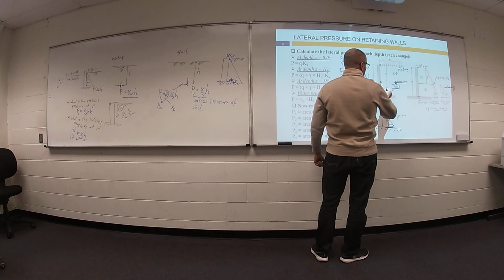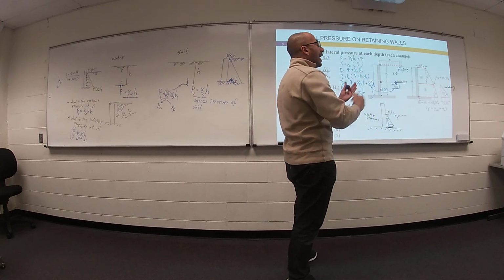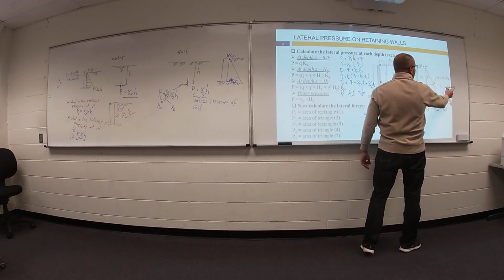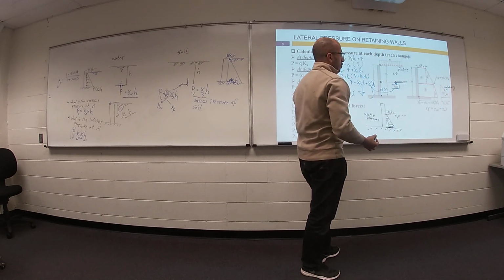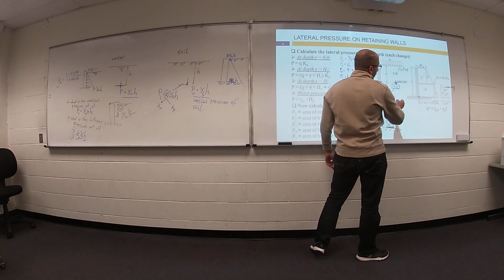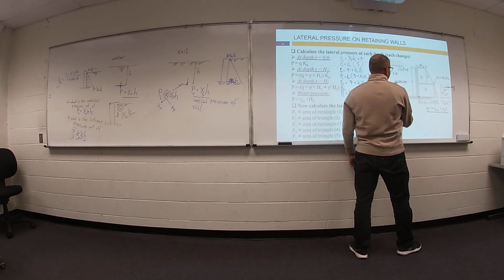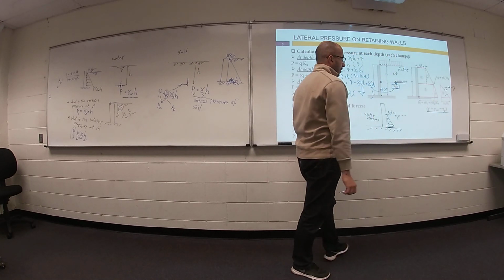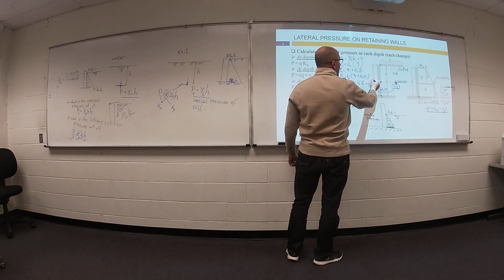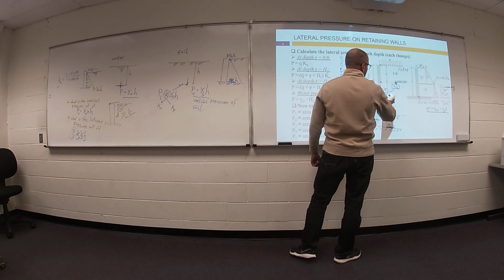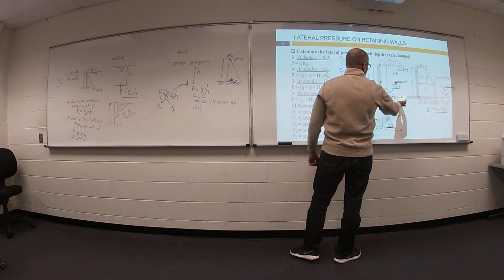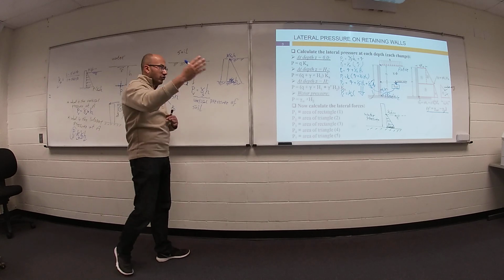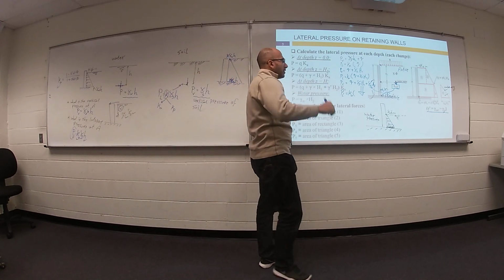No, because gamma saturation is a combination of soil and water, both of them in the same value, but you take care of water before. So what is the value here? Your value here equals gamma saturation of soil minus gamma water. This term is called gamma effective, the effective unit weight of soil. In soil mechanics, everything will be covered on this point: gamma soil, gamma saturation, gamma effective, all of this stuff.